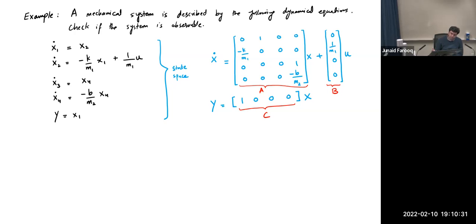But for controllability, observability doesn't matter, right? Because why would it matter if you want to observe the state? State observation only requires A and C. And same thing for controllability. If the input is reflected at the output, it doesn't say anything about whether it can control the state variables or not.